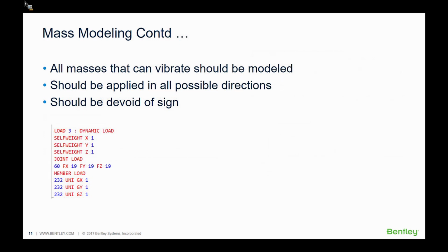Now, how to include the masses in the analysis? Different software have different ways of modeling the masses. I'm going to focus mainly on STAAD Pro in our Tech Talk today. In STAAD Pro, the masses are modeled as loads.